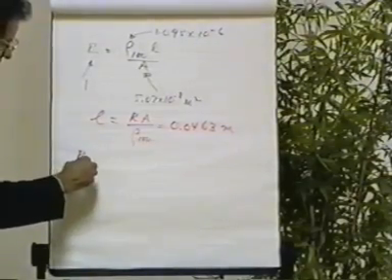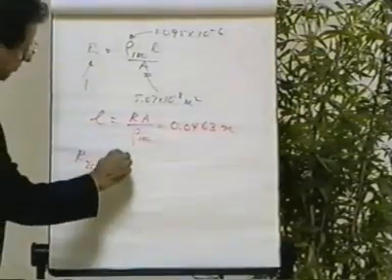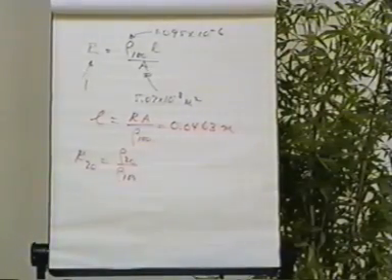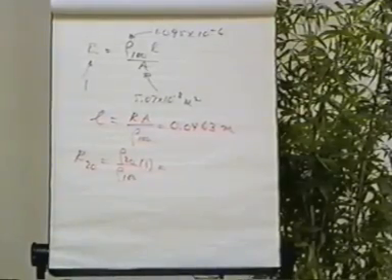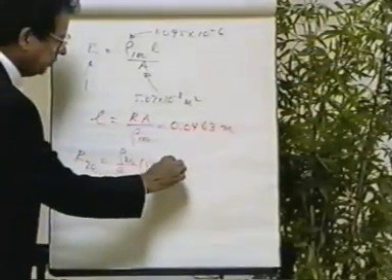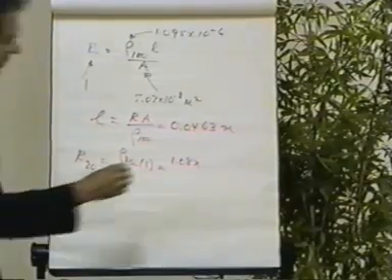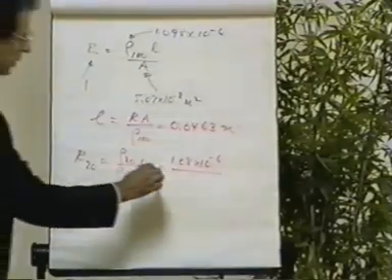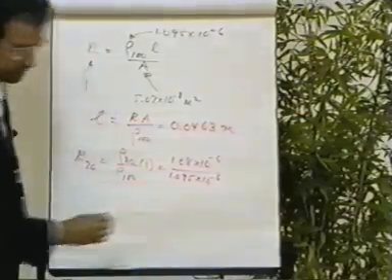The resistance of that same piece now at 20 degrees is a proportionality between rho at 20 and rho at 100 times the 1 ohm. And the rho at 20 is given from the beginning of the problem statement, we can find it in the table, as 1.08 times 10 to the minus 6, and the rho at 100 is 1.095 times 10 to the minus 6.